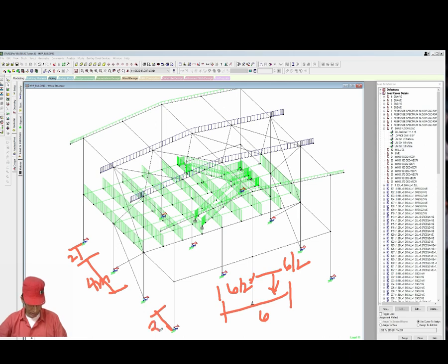So 6 meter. And this corner column will have a tributary area of 2 meter from this direction. This is only for wall cladding load, and from this direction 3 meter. So we have for interior column Z direction, tributary area is 4 meter.